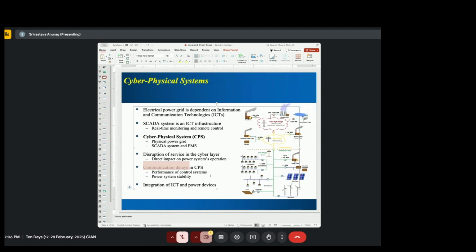So if you're solving power flow, you're only looking at steady state behavior of this physical system, right? If you're doing transient stability analysis, then you're looking at the transient and dynamic system behavior. For that, you need more data because you need a dynamic system state at each generating plant and transmission line. If you don't have those data and you still want to do dynamic, you cannot do that, right? So unless we have data for dynamic simulation, you cannot do a dynamic cyber physical simulation either.